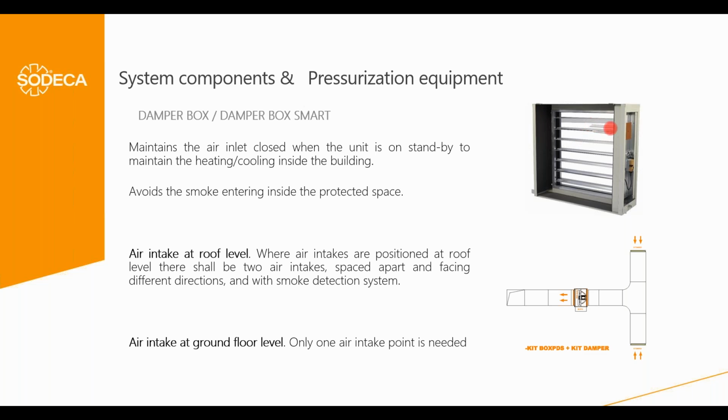We have here the smoke sensor and the Belimo motor, and as I mentioned before, if there is smoke around the damper, the system closes it very quickly, and opens it very quickly. These dampers open and close in less than 2.5 seconds.